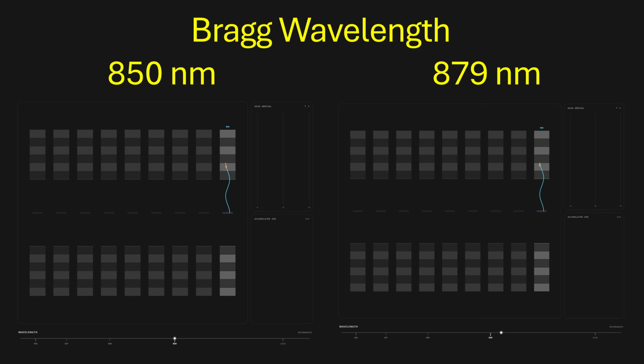Furthermore, the path length of the cavity is not a single value because the light is reflected as an optical field at every layer of the Bragg reflector at the same time. This is not an issue for the 850 nanometer light because the optical path length of the layers of the Bragg reflector are exactly 1/4 of 850 nanometers, and every other surface is a low to high refractive index transition that gives a 180-degree phase shift.